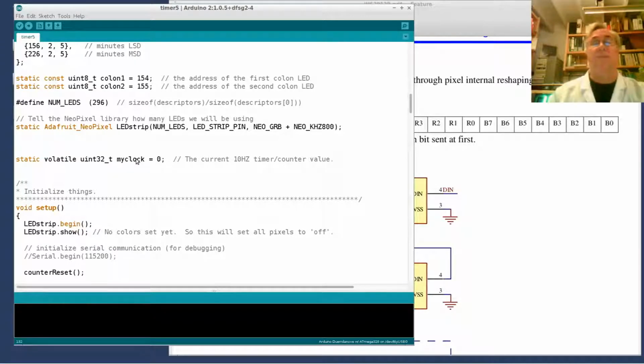Remember, an interrupt tells the CPU to stop doing what it's doing, go off, do something else, and then resume what it's doing. Well, you need to make sure that the compiler always reads the value of this variable. You can Google search on what it means to create volatile variables in C and C++, and learn all about that. The short of it is, if you got variables in an interrupt handler that you also want to read in your regular old code, make it volatile.